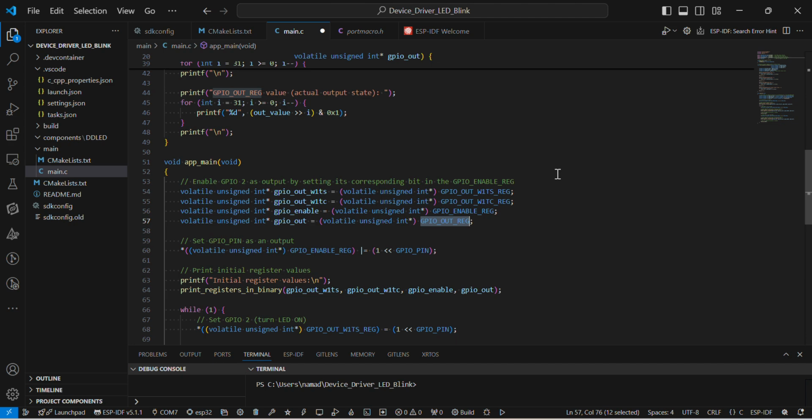A register is a hardware dependent variable. If the compiler mistakenly optimizes that register into some other mapping, then when you try to access it, you can't, because the code doesn't change this specific variable, only the hardware does. So if the compiler optimizes it, the hardware can't change it, or you can't read or write the register properly.